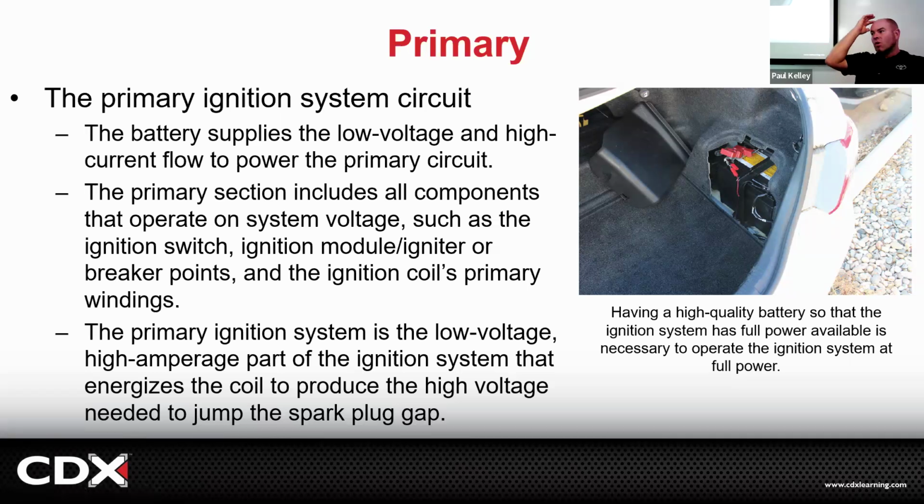Yeah. So basically, when your alternator fails, you're just running your system off the battery. When your alternator's running, you're going to get your 13.9, your 14.2, your ignition's happy. But when your alternator fails, your battery voltage is dwindling. Your primary voltage is going down right along with your battery, right? So you've got to think the primary voltage is all tied into your battery, your alternator, all that type of stuff. So if you've got a battery or alternator issue, I agree that could cause ignition problems.